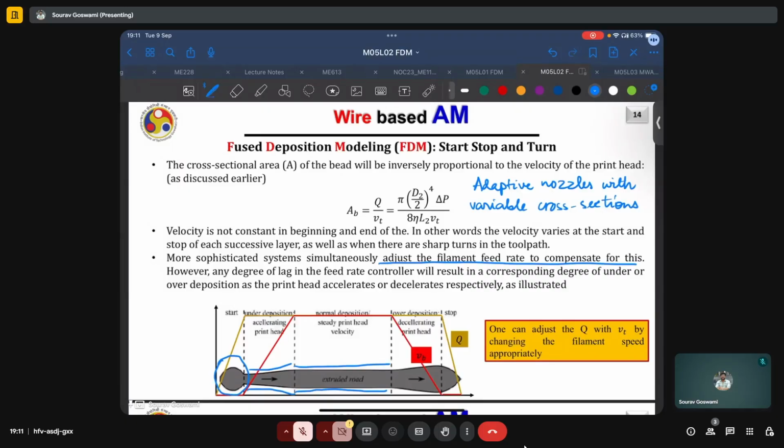Whereas the area filling can be done with a coarser beam spot size, or at a higher speed. However, if we are using an adaptive nozzle, what we can do is use the same nozzle for both the perimeter and the infill passes. At the perimeter, we just constrict the cross section, whereas for the infill, we increase the cross section.